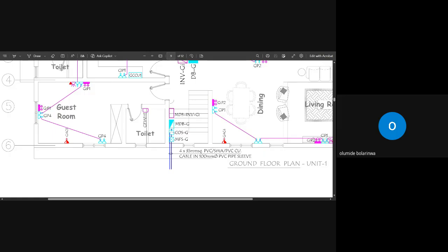Are you going to put that 39 meters in your bill? Can someone tell me why we should not? Are we going to put 39 meters in that bill, or we add something to it? Sir, I think we probably add allowance for space, connection, wastage and cutting off. I think we add something to it, sir. God bless you. You must add slack to it. Do you know the reason why we want to add slack to it? Ask me why.